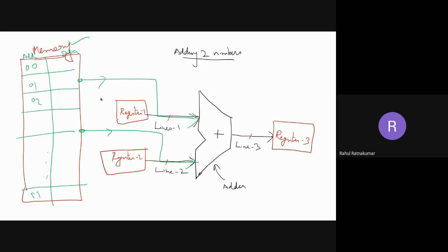Instead of directly putting the memory variable into the processor and making the processor wait, we give values to the registers only. We may also have a connection from the output register to the memory, so that it can store. So memory can not only load, it can also store. Loading means taking a value from the memory and loading it to some memory element like a register, flip flop, or RAM. And storing means some result or number input from the user has to be stored somewhere for the future.